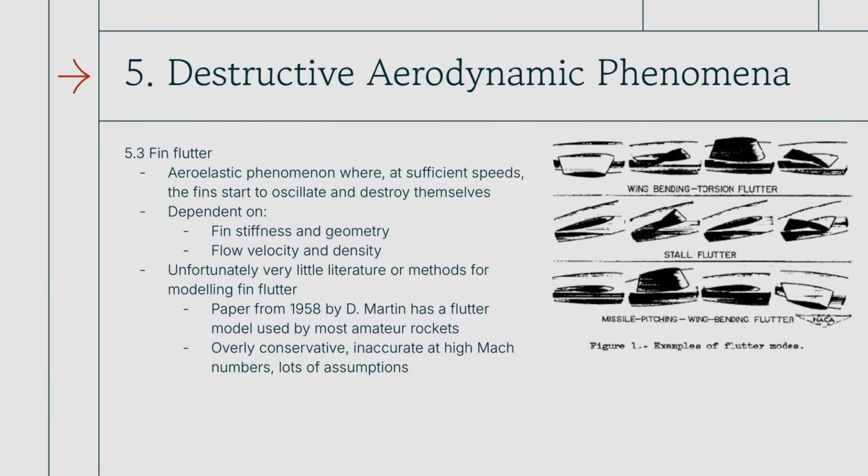And so this is dependent a lot on how strong your fins are, so how stiff they are, the geometry of your fins as well, and the flow velocity and density, obviously, so how fast you're going. Essentially, what you're going to do is calculate, for the thickness and strength of the fin you have, how fast you need to go before this flutter phenomenon will happen.